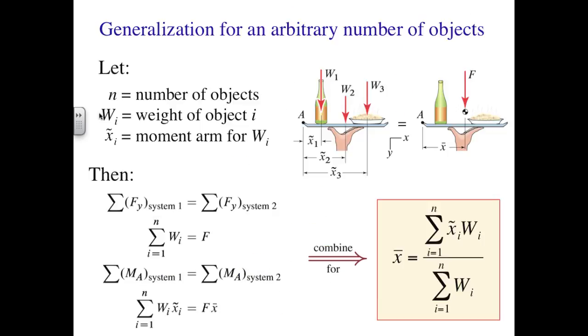For a more general number of objects, we'll call it n, the center of gravity is represented as the boxed expression at lower right. It is calculated as an average of the locations of all the objects, with each location weighted by its physical weight. As the phrase "weight weighted" is unfortunate, we could instead say that the center of gravity is a force-weighted average